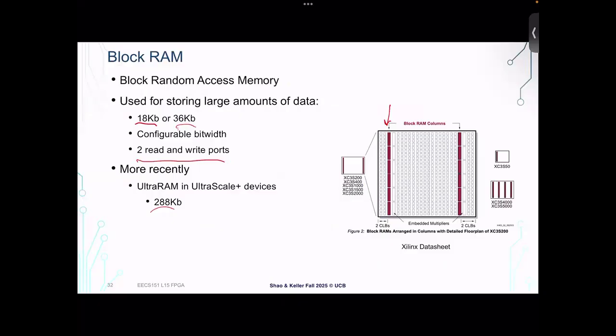One difference is that typically with SRAMs, you can generate them to an arbitrary size based on the specific configuration that you need. Whereas with block RAMs, you're restricted to mapping onto the specific sizes that are provided on the FPGA. If it's too big, then you have wasted space. If it's too small, then you have to compose it out of multiple ones. The details in Verilog of how you actually instantiate them are also different, so I would refer you to the two different flavors of lab for the details on that.